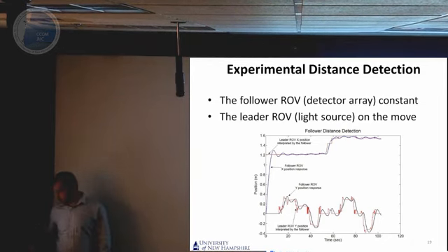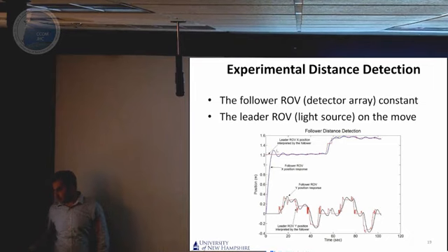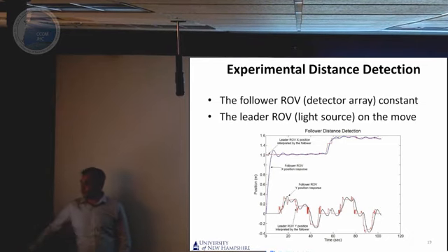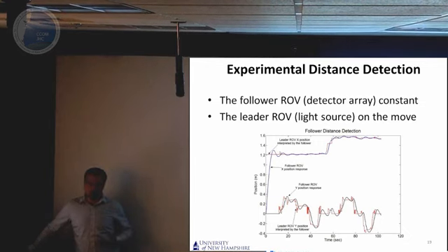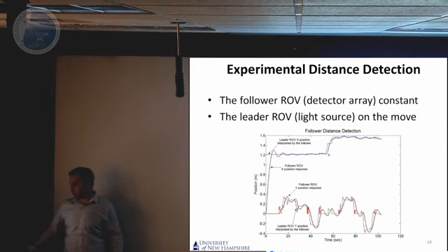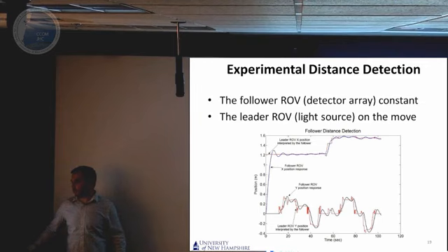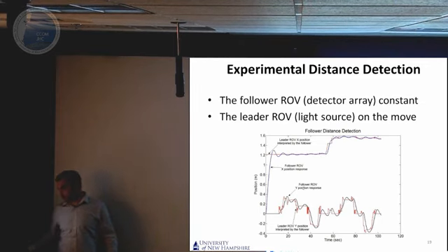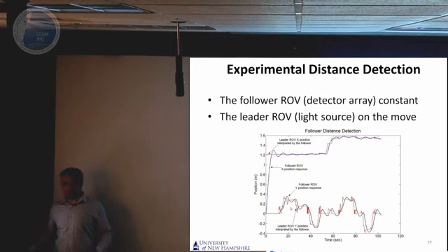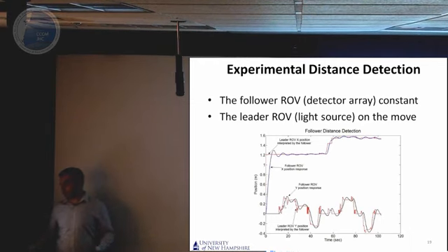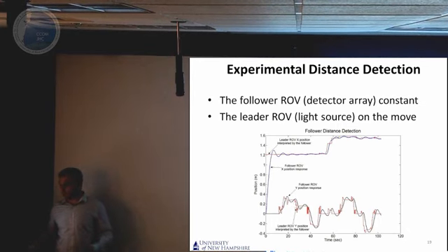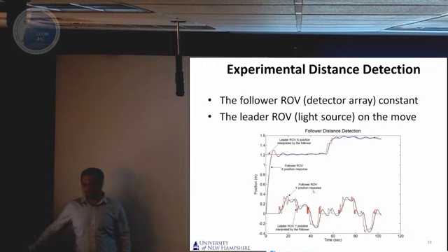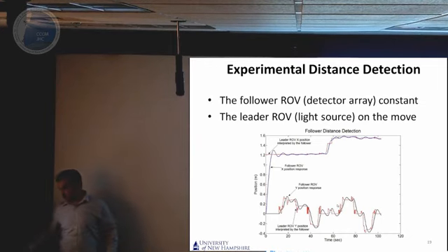First of all, the detection capability of the algorithm determines the control system. For X, it determined a constant, almost like a step function. Therefore, the problem turned out to be a regulation problem, where it could easily regulate these command signals. For example, at time 50, it's commanded to go from 1.2 to 1.6. However, if you look at the Y, since the generated trajectory is not as smooth as in the X case, this problem is almost like a trajectory problem where the trajectory is changing over time. So we see that the PD controller is not performing well here. It tries to track, but it's not very efficient.